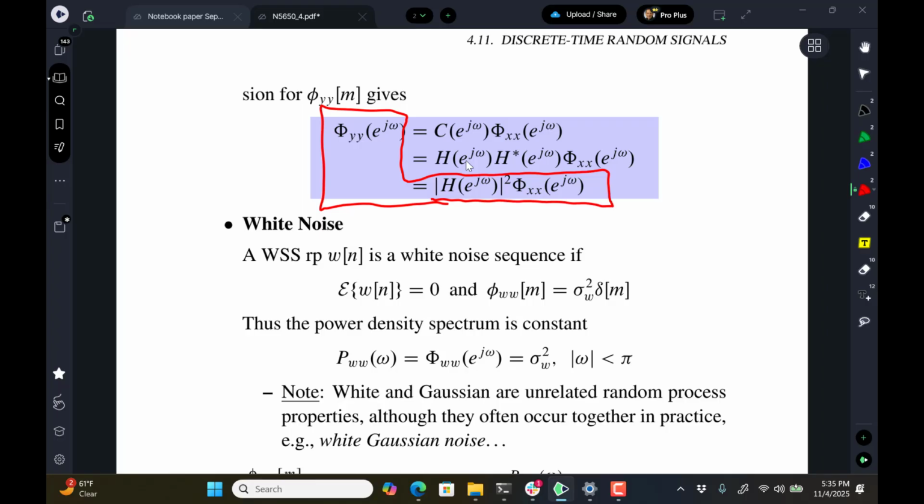What did I have to do on my space radio when I was working on part of the transmitter? Remember I talked about the NTIA last week and having to meet the NTIA spectral mask requirements. So I just had to come up with a filter design that could shape the raw transmitter output, remove some of the side lobes on it so that it would fit into this mask that the NTIA provides for spectral emissions. And that was just taking the magnitude squared of the filter I designed, putting into it the theoretical spectrum, and seeing that that worked.